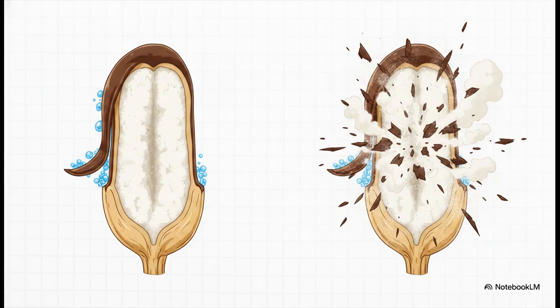High-efficiency milling is absolutely not a process of blunt force crushing. It is a highly calibrated structural disassembly. You have to surgically separate the tough outer bran and aleurone granules from the starchy endosperm. And that separation is dictated entirely by aggressive, mathematically precise moisture control.